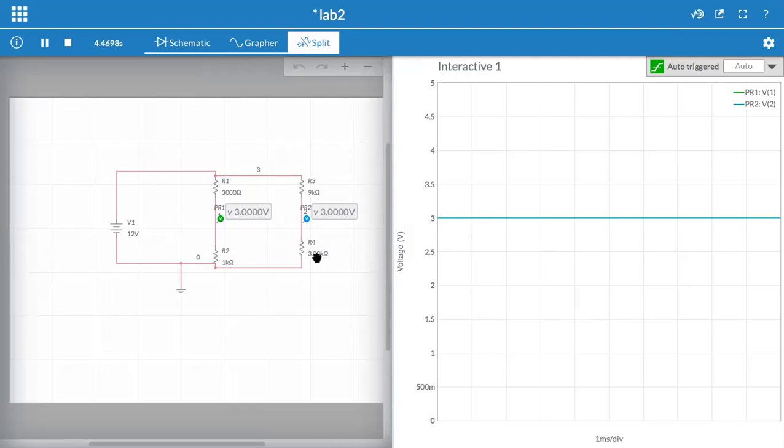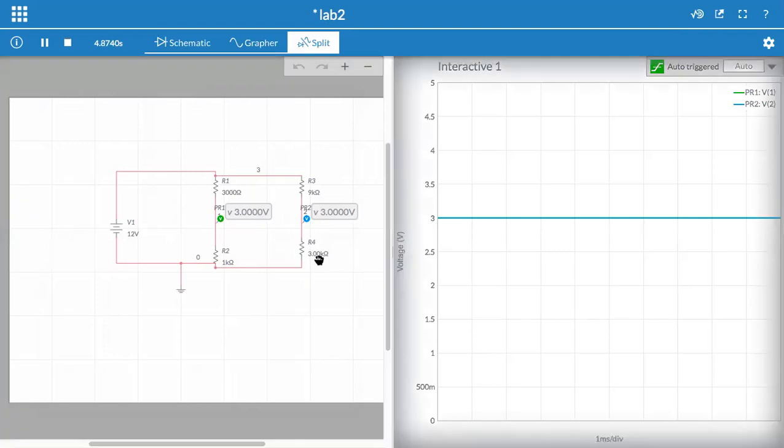So let's suppose, well, this guy right here will be our sensor. So that's a temperature sensor. As temperature goes up and down, my sensor's resistance will go up and down. Right now it's 3000. So at 3000, the bridge is perfectly balanced. What if I increase and decrease my sensor resistance? So I will increase sensor resistance.